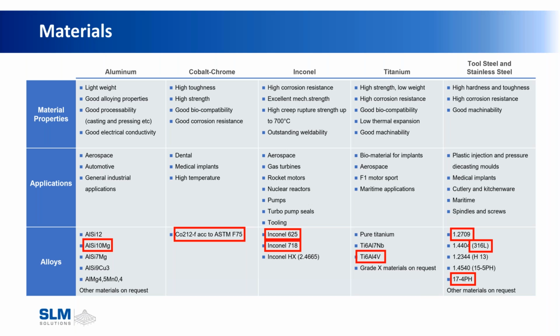And one of the benefits of powder bed fusion is that the cost of material is pretty insignificant to the total cost of the process. So if your typically manufactured part is in 316 and you wanted to print it, maybe the cost of material to move up to, say, Inconel 718 is going to be pretty small compared to the overall process cost.